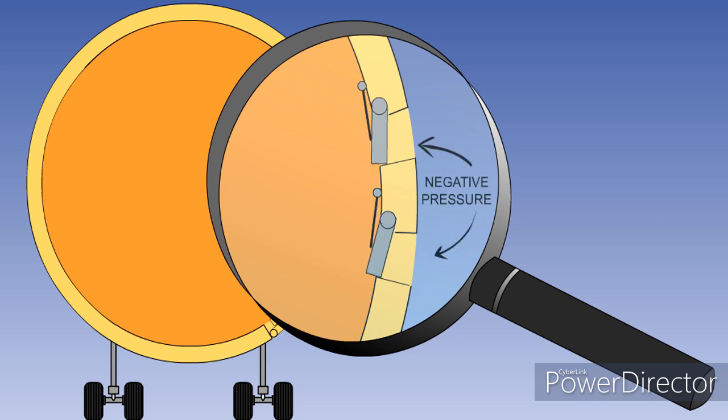They will open if the pressure outside the aircraft exceeds that inside by 0.5 to 1.0 psi. There must also be 2 of these valves. The inwards and outwards safety valves may be combined together in one unit, or may be completely separate components. They are positioned above the aircraft flotation line, so that in the event of a landing on water, they will not allow the water to flow into the aircraft.